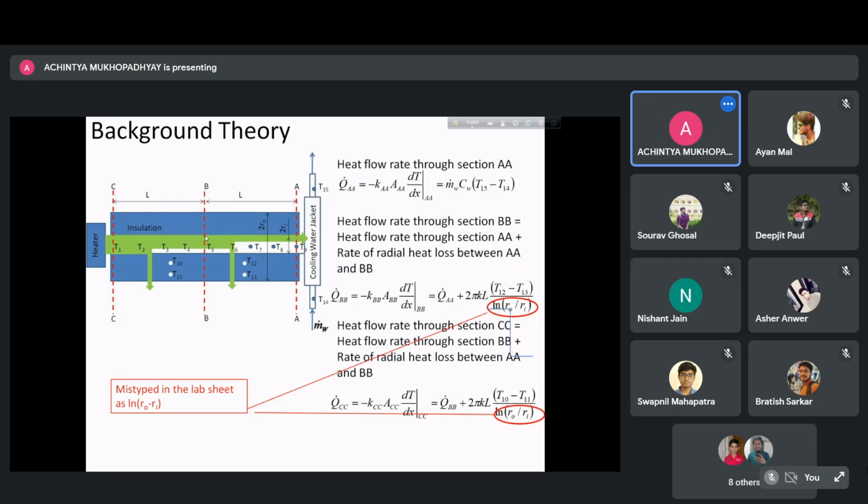simple energy balance. How could we do the energy balance? From the convective heat transfer, h (T minus T infinity) times perimeter times dx. Integrating this, you could have got it. Yes, sir. But here, experimentally, that is not easy to do.